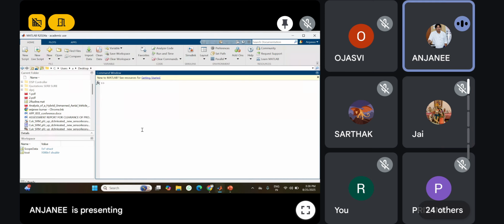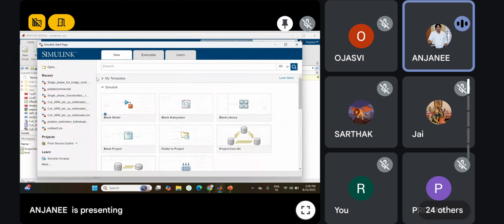So Dr. Simanjit sir has discussed how to write the commands, what the different command systems are, to compute the mathematical things. Here, we will see how we can use the MATLAB Simulink blocks to design any system. So the first thing, just go to this New, the plus sign, and scroll it down. You see that at the last, there is a Simulink model. So you just simply click on Simulink model and this window will come.